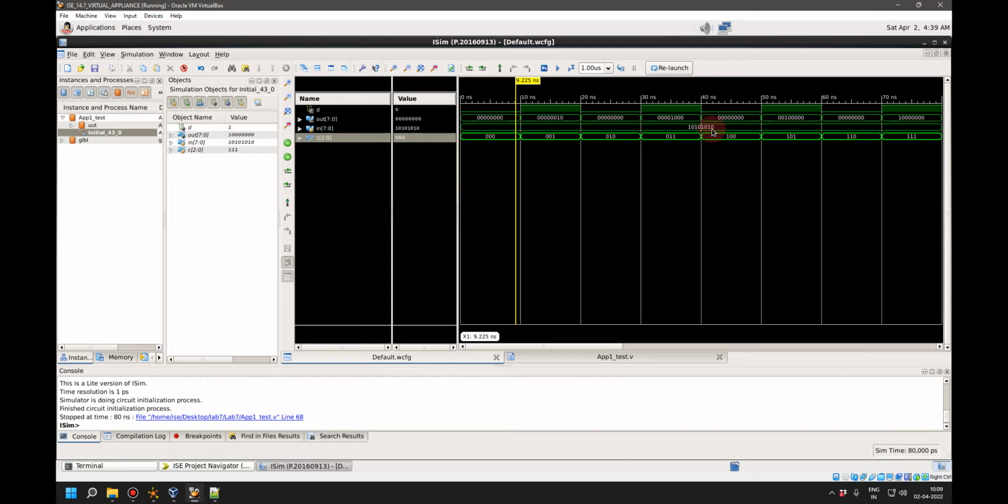So instead of transmitting 8 different lines from chip A to chip B, I am transmitting only a single line, which is the D out here, and I am using the control signals to regenerate that particular data, right? So when I am selecting that particular control line, the data which is available here is being reflected out here. So this is 1 out here, so that 1 is coming here. So this is what we discussed as one of the applications of using a mux and an encoder together.